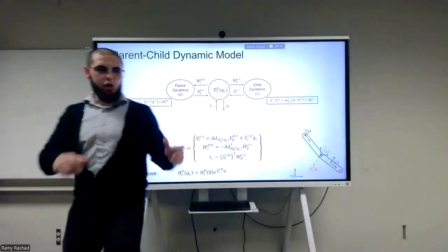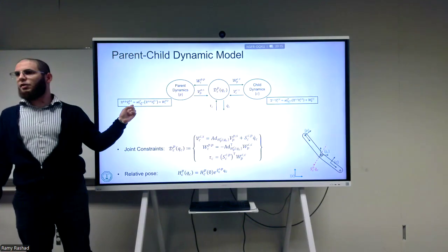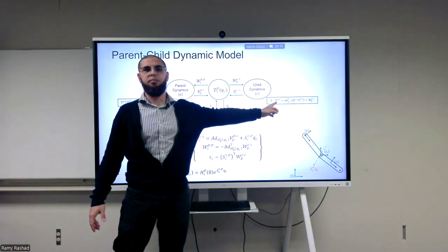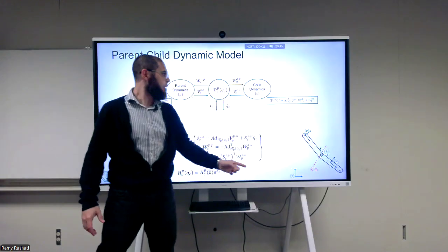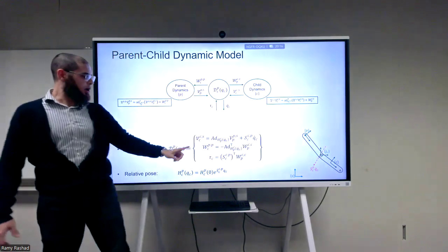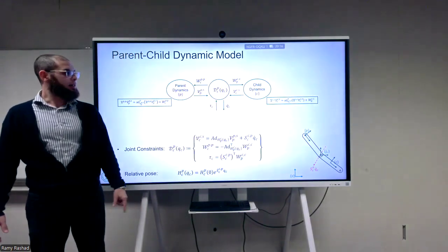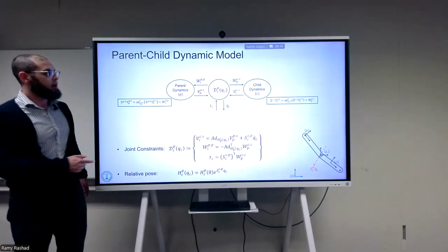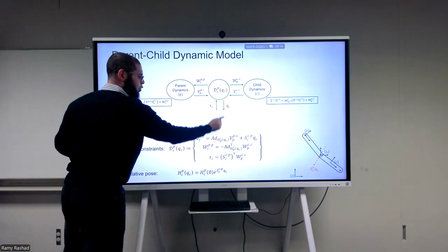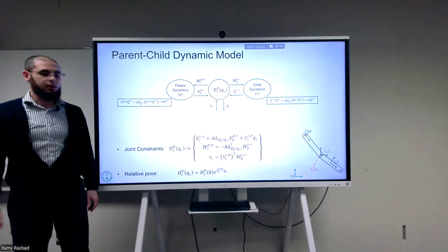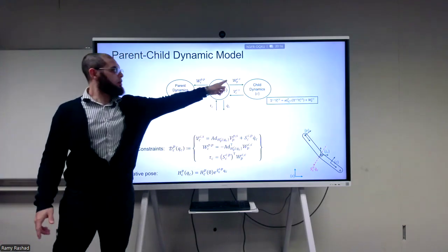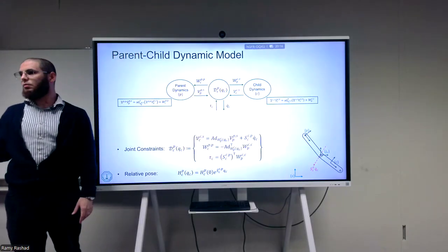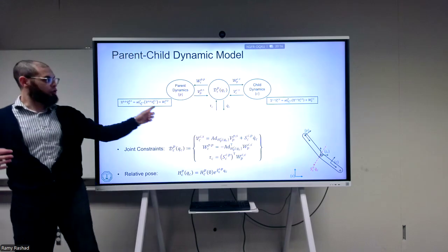First, you need the dynamic equation of the parent rigid body, given by the Euler-Poincare equation. You need another dynamic equation of the child body, given by another Euler-Poincare equation. And inside of here, there are 3 equations that we just discussed that correspond to the joint. What the joint does is that it constrains the twists and the Q dot to satisfy this equation, and it also constrains the wrenches and the torque to satisfy these 2 equations. So we have 3 constraint equations and 2 differential equations.